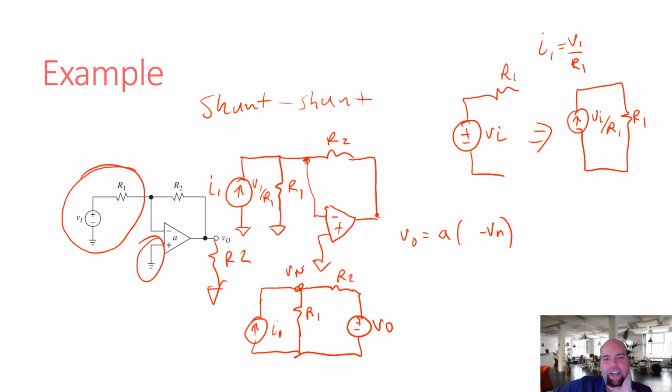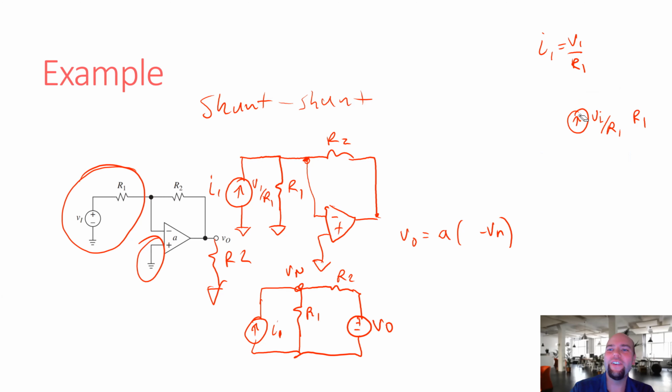So let's do something different, actually. So we could do superposition. The book likes superposition. Superposition would be fairly easy, right? Because it would be one voltage divider and then the current flowing through two resistors in parallel. So it would be pretty easy. But at the risk of making an already disastrous lecture worse, let's use a totally different technique for finding this. So just to show that you can do it, let's use node voltage to find Vn.